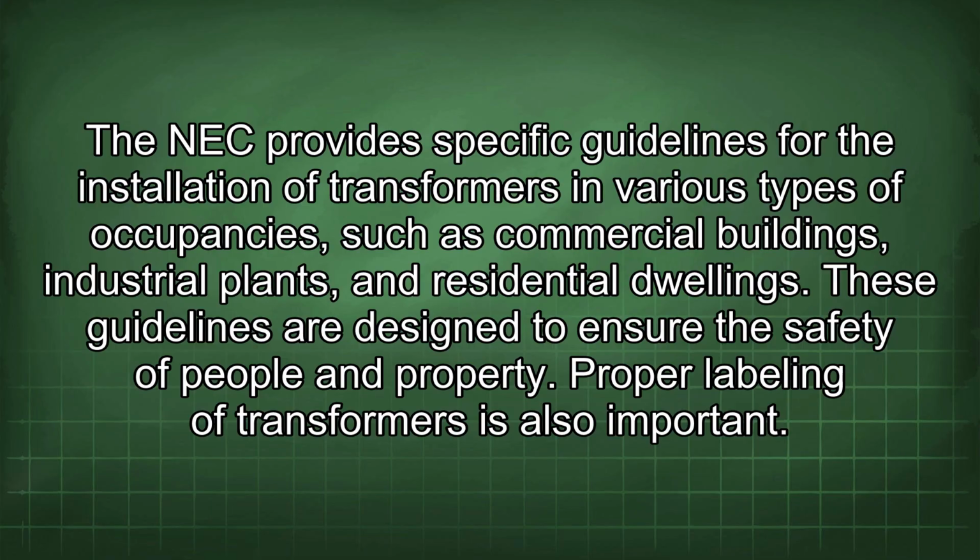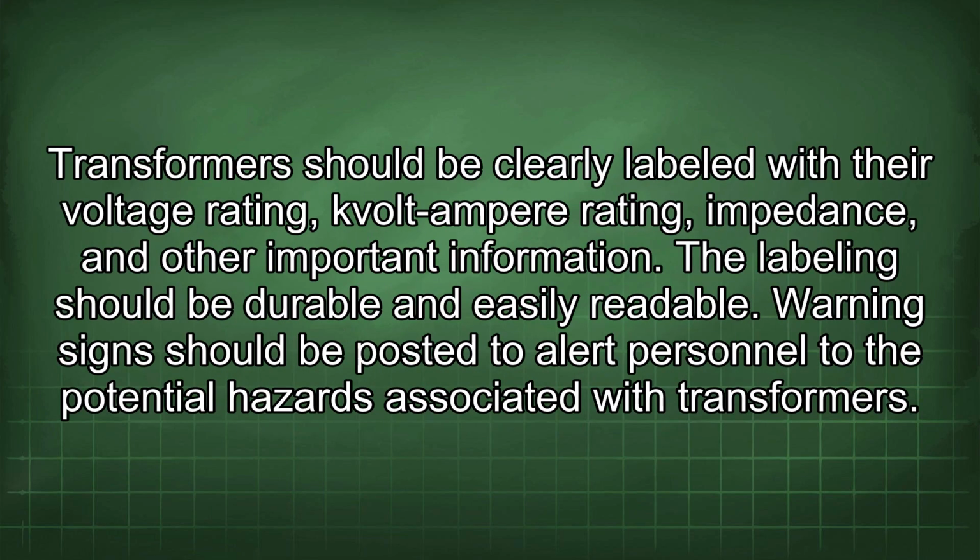Proper labeling of transformers is also important. Transformers should be clearly labeled with their voltage rating, kVA rating, impedance, and other important information. The labeling should be durable and easily readable. Warning signs should be posted to alert personnel to the potential hazards associated with transformers.